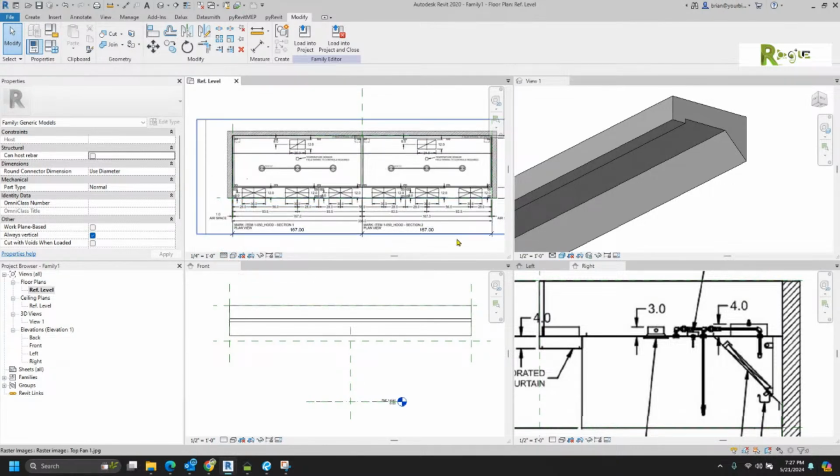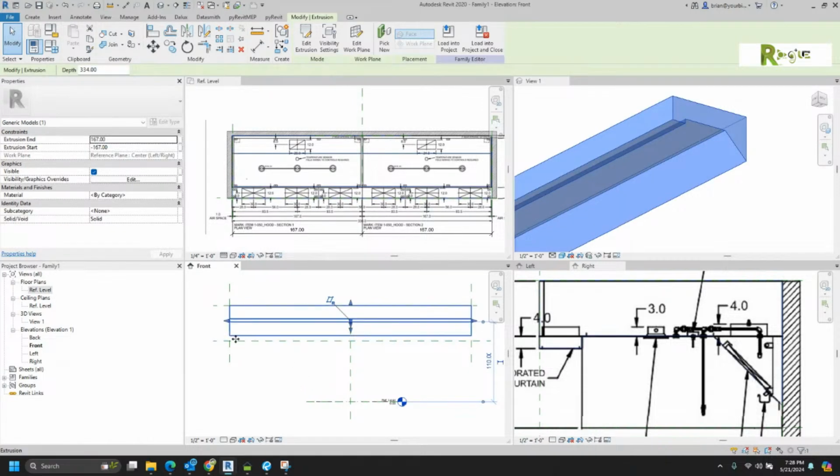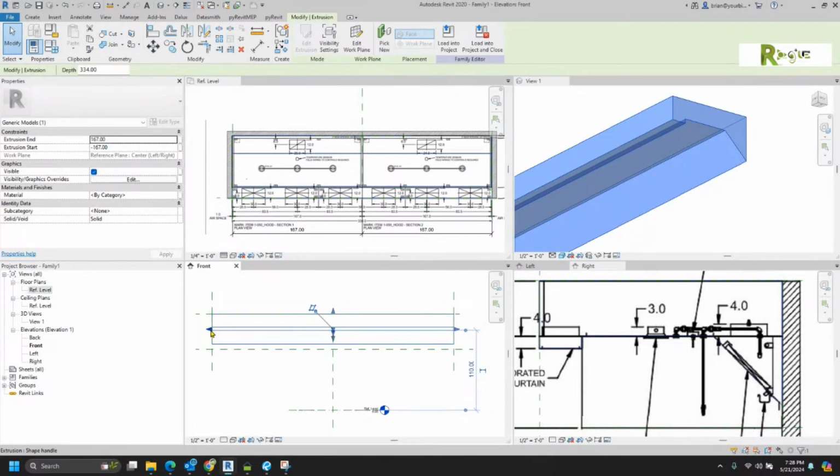Right? Yeah. So when I did that stretch, one of the things that you'd want to keep in mind, Ginger, is it did not stick to that reference plane unless, when I do the stretch and hit it, I hit this little lock symbol. So this stretch should have looked like this and hit that stop symbol.